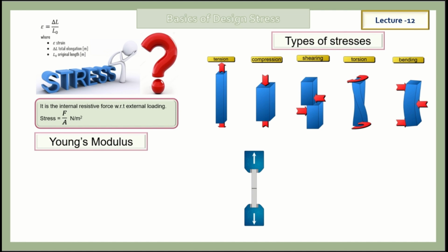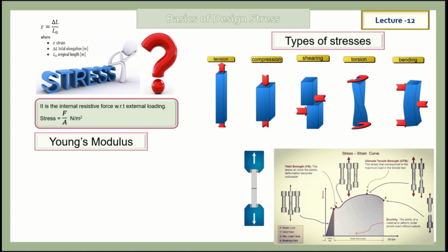What is modulus, and how do we find Young's modulus from experiments? Young's modulus means stress by strain. In college days, we generally know Young's modulus means stress by strain. In our college days, we did one test like the UTM test, that means the tensile test. By using this tensile test, we will find the Young's modulus, guys. So let's take an example, that is the tensile test.